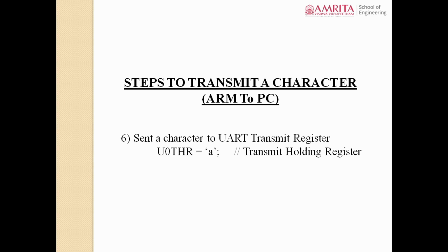So how will I access the shift register? How can I load this A to that shift register? By using a register known as the THR register. If you are sending a character to THR, finally it is sent to the shift register, right? So before sending the data to the shift register or THR, what should you do? You need to check whether the shift register is empty, right? If the shift register is empty, what does it mean?